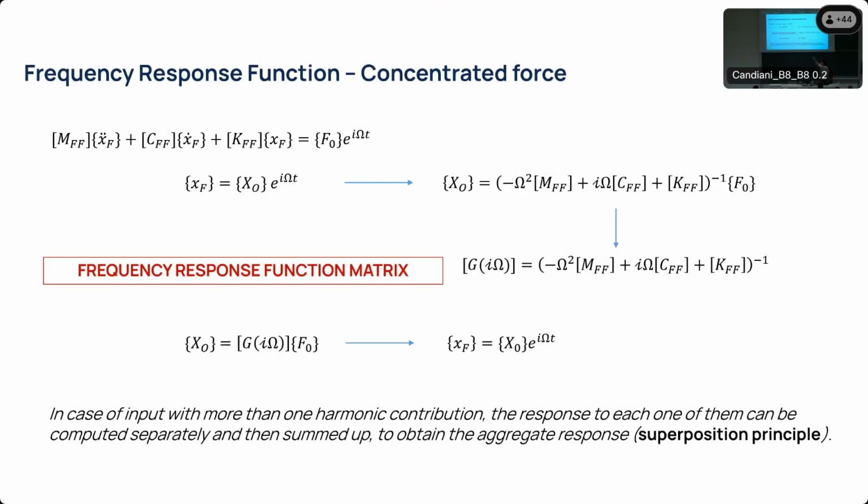If we want to solve a system of equations of motion, those equations are differential equations, so we can impose a general solution shape, which will have the same frequency as our input force, that we know because we decide the frequency span of our force input. So we can impose a general solution shape to our vector of free coordinates. We can derive it 2 times and then create the denominator that we already saw during other courses.